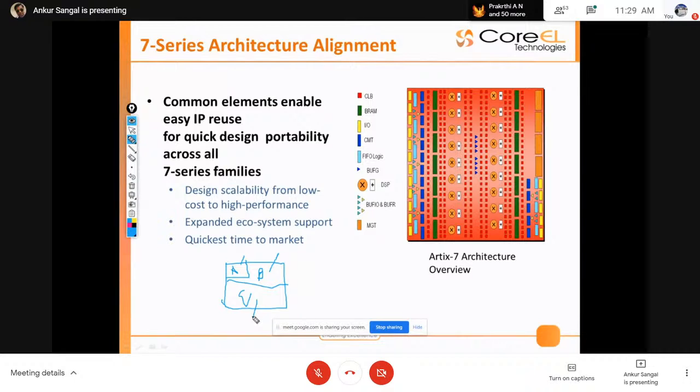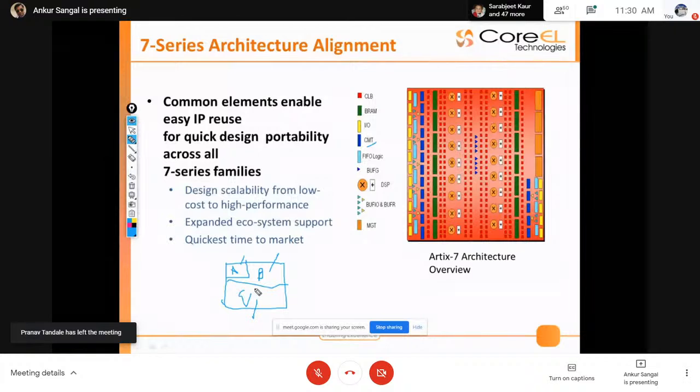Okay, so these different clocks you need if you want to run this design. With the help of CMT, you can generate multiple clocks internally. No need to take any tension. The CMT automatically manages, and CMT works in 2 criteria. One is MMCM, mixed mode clock manager, and another one is PLL. PLL stands for phase locked loop.